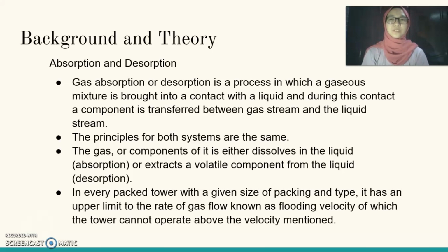Okay, for this report, I'm going to present about the background and the theory for absorption and desorption. Gas absorption or desorption is a process in which a gaseous mixture is brought into contact with a liquid, and during this contact, a component is transferred between the gas stream and the liquid stream. The principles for both systems are the same. The gas is either dissolved in the liquid, which is absorption, or a volatile compound is extracted from the liquid, which is desorption.